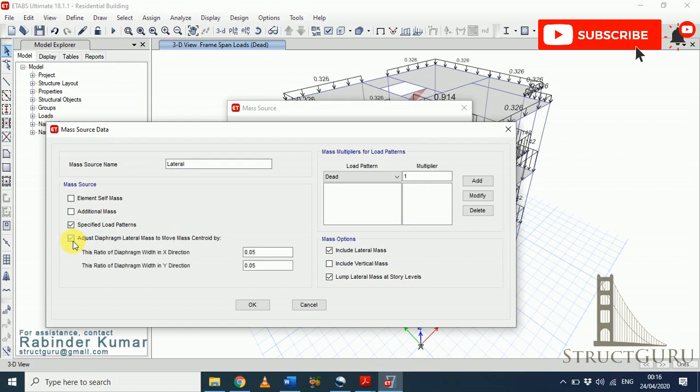Similarly, the fourth option is adjust diaphragm lateral mass to move mass centroid by. This dialog box is basically related to eccentricity. So normally we don't do anything with this dialog box. If you want to change the values, you can, but leave it as it is for this stage. So let's specify the load pattern as given in our ASCE and Indian code.